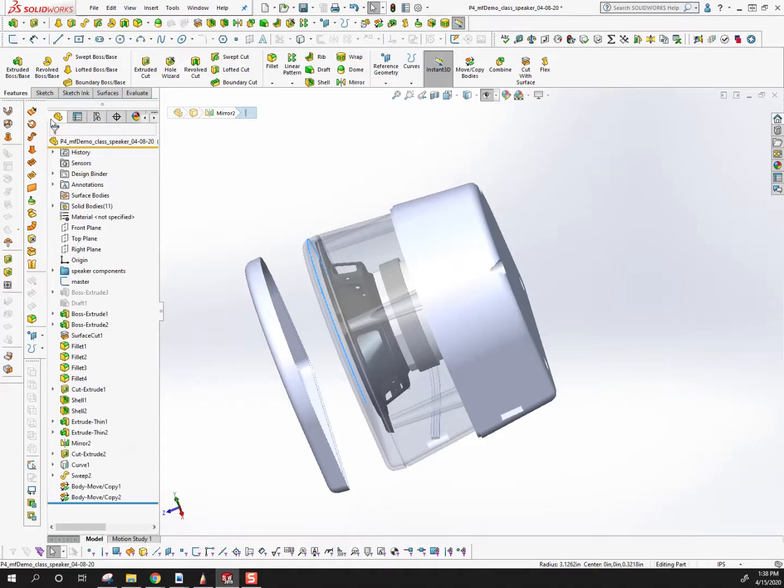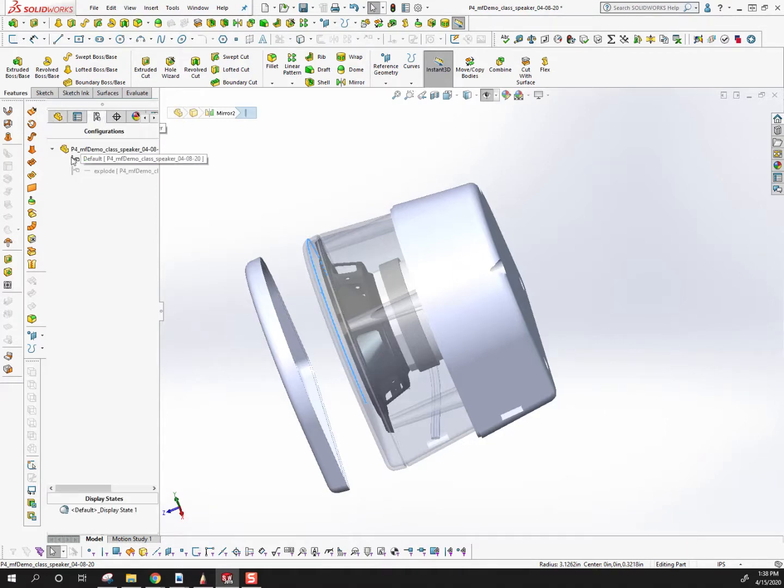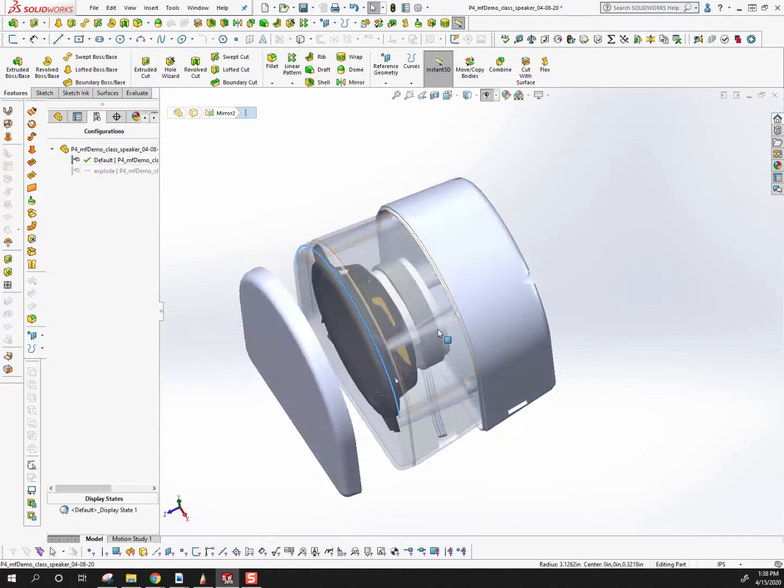In which case, configurations are helpful if, for example, way back when I worked on a water bottle with a flip top, and so I used a configuration for the open view and the closed view. It was helpful for meetings to quickly switch between the two and talk about what it looks like open, what it looks like closed. There were also more moving parts. So it's more useful if you're mainly viewing things in SOLIDWORKS and discussing things and being able to switch between two. If the goal is Keyshot, it's maybe not as necessary. It's just a handy thing to be aware of, I guess.